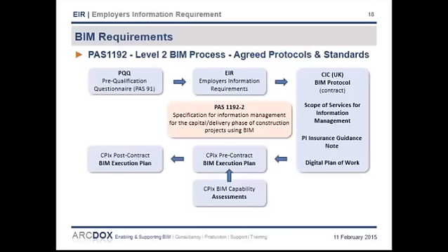Then once appointed, the project information manager, who will typically be the lead consultant at design stage, will assemble the post-contract BIM execution plan for design stage, and together with the team, they will maintain that for the duration of that stage. We would also recommend that the post-contract BIP for design stage gets included in the tender documents for contractors, so they have visibility as to how BIM has developed up to that stage. The contractor will then typically take on the role of project information manager for construction stage, and together with their subcontractors will develop the post-contract BIP for construction stage.